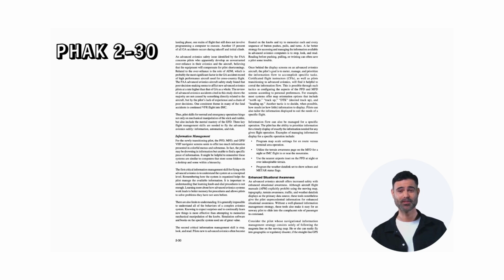The review of advanced avionics accidents cited in this study shows the majority are not caused by something directly related to the aircraft, but by the pilot's lack of experience and a chain of poor decisions. One consistent theme in many of the fatal accidents is continued VFR flight into IMC. Thus, pilot skills for normal and emergency operations hinge not only on mechanical manipulation of the stick and rudder, but also include the mental mastery of the EFD. Three key flight management skills are needed to fly the advanced avionics safely: information, automation, and risk.